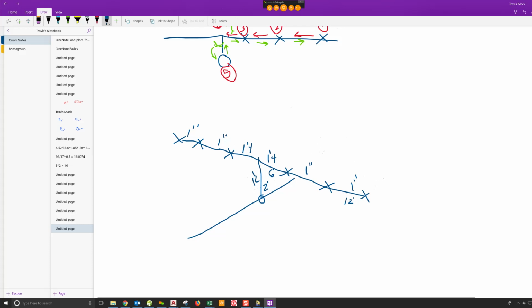Okay, let's stick with K5.6. And let's say this is a light hazard building and our sprinklers are covering 160 square foot. So what is my minimum flow per sprinkler? It's light hazard, so what's the density of light hazard? 0.1. So what is my minimum flow out of each sprinkler? 16 GPM. Okay. So we know Q1 equals 16. What is P1? Q divided by K. 16 divided by 5.6 and square that. 8.2. Do you guys get that?